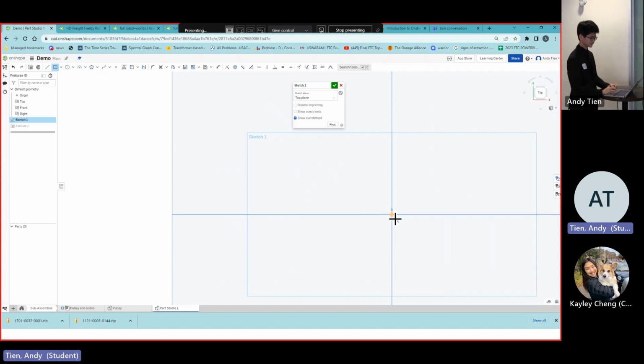If I set this as my center, I can drag out a rectangle and it's going to be symmetrical both in the X and Y axes, because what you first define is the center, and then you're just defining another vertice on the rectangle to draw it out. So over here, you can see I created a rectangle and what's defined is the center point and another point.